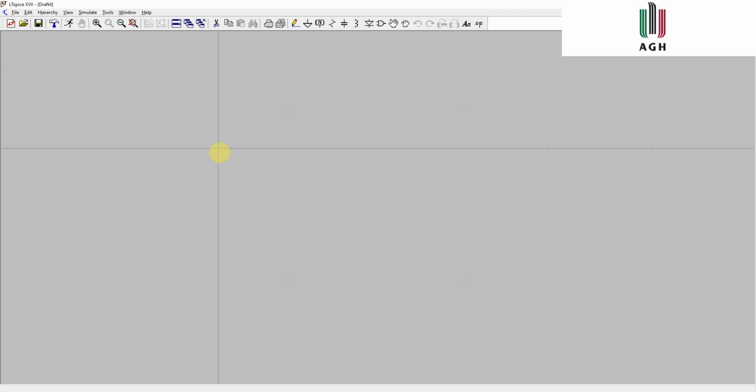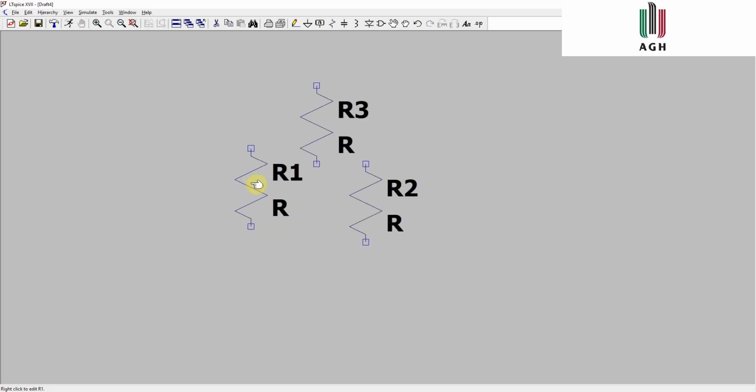F3 is a shortcut for a wire, which can be drawn vertically or horizontally, making perpendicular lines, which are the wires of our desired circuit. R is for resistor, C is for capacitor, L gives us coil, G gives us ground. By clicking delete we obtain the scissors, which will allow us to cut unimportant and unwished parts of our circuit.